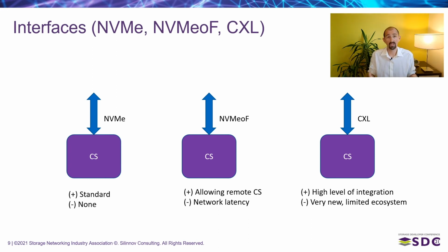For example, we can use vendor-specific commands, which are available in the NVMe specification. Or we can use different namespaces with different actions. For example, one namespace for an acceleration algorithm, or another namespace just for the compression, and so on.